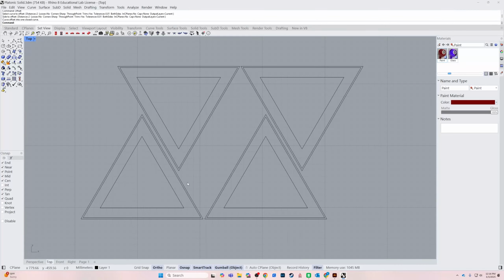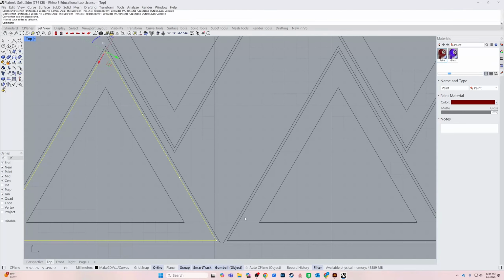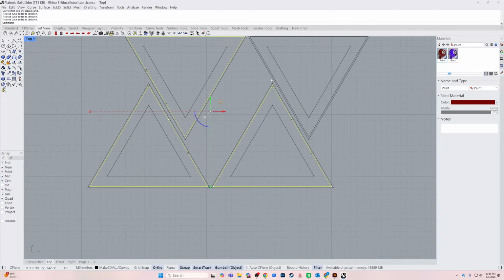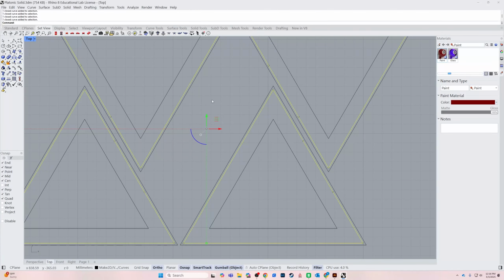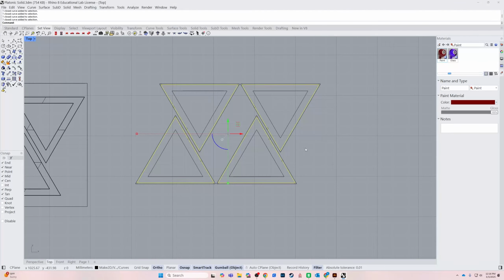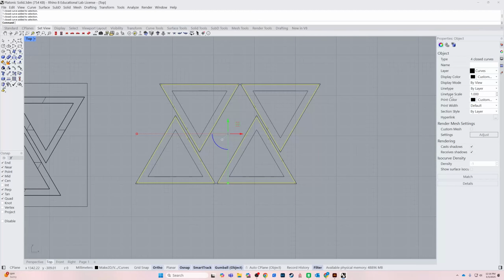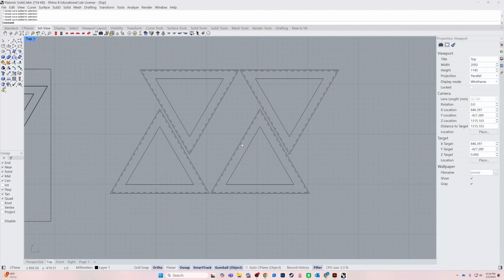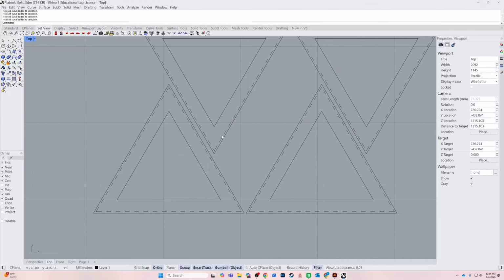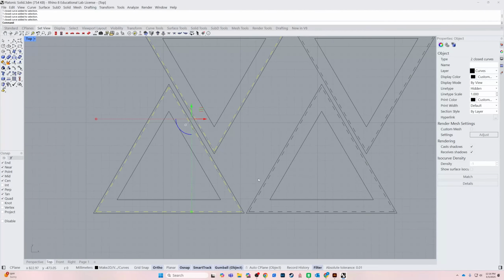So I want to create a secondary color represented for these guidelines that I've got here. So selecting those interior lines, I'm going to go to properties here. No, properties, sorry, wrong one. Properties, and then line type here, I'm going to change this to hidden. And so that's going to give me these dashed lines. Next, I also want to change the color of these lines.